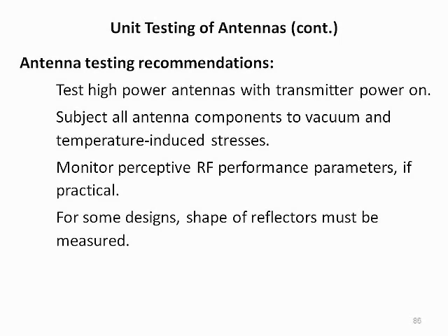Pertinent RF performance parameters should be monitored during the test to the extent practical, although this may be difficult in a thermal vacuum test environment. For some designs, the shape of reflectors must be measured before, during, and after test to determine if shape changes are great enough to affect RF performance.